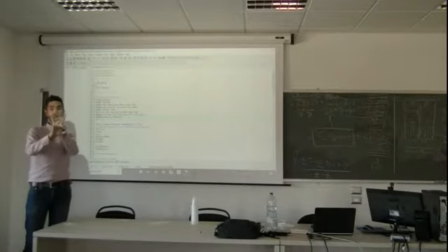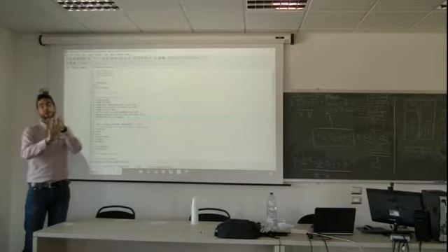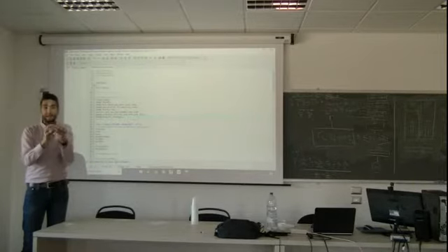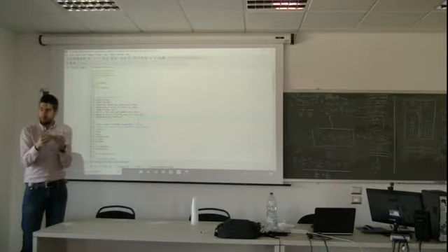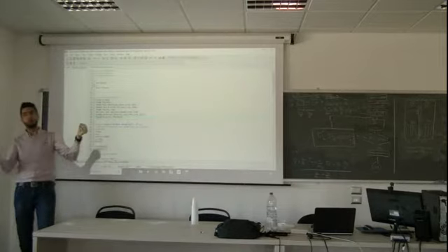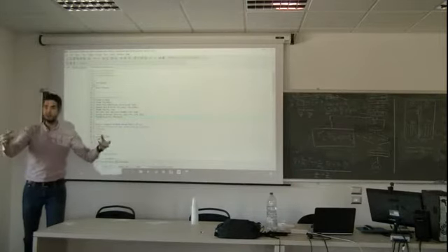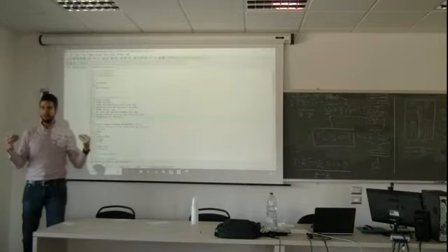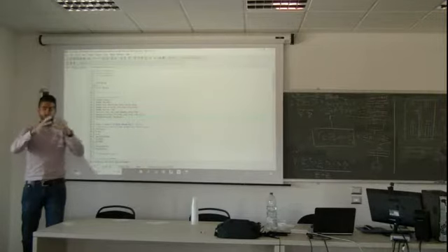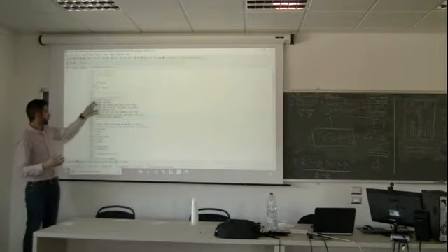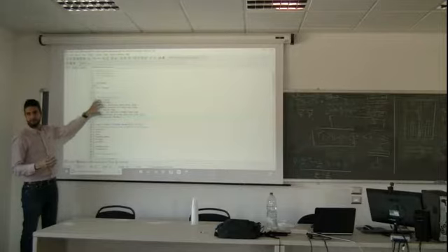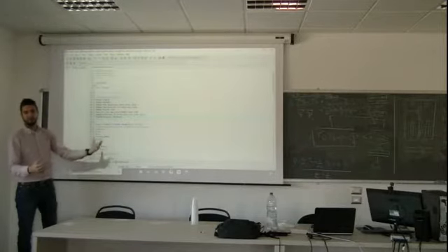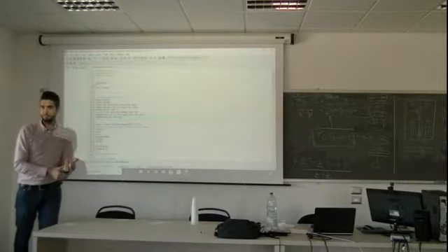So imagine I want to compute 2 hours every second. So one dimension is 7,200. And depending on the geometrical number of nodes, I will have matrices of a lot of elements. Each element requires certain bytes to be stored. Depending on whether it's double or float, you require more memory or less memory. If you are working with huge matrices, then put a static. And then the software will use part of RAM and part of your hard drive. Okay?